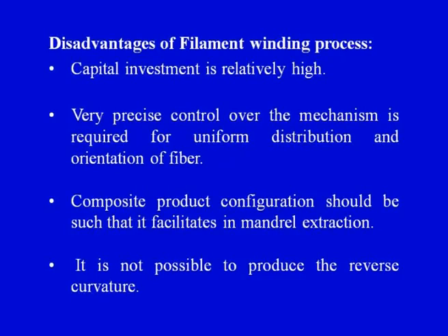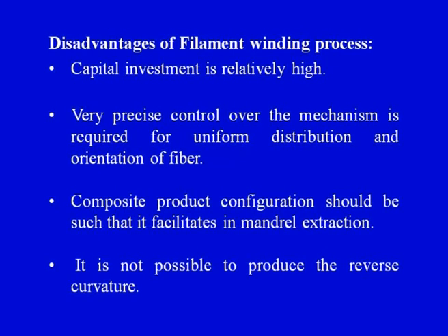Now, what are the disadvantages of the filament winding process? Capital investment is relatively high because we have to procure a filament winding machine. So, the capital investment is therefore relatively high. Very precise control of the mechanism is required for uniform distribution and orientation of fiber.